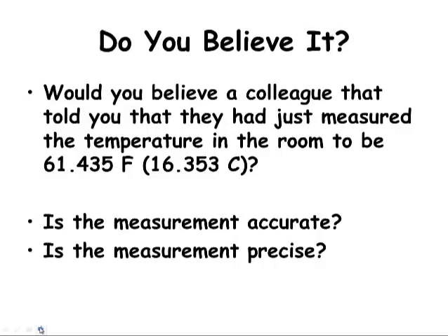It would also be important for my colleague to communicate how the temperature sensor was calibrated to such a precision and accuracy. Calibration is always important. Without proper documentation, I would question, be uncertain about what my colleague had told me. If my colleague provides the proper documentation, then I would trust the information. To answer the specific questions listed, the measurement is precise. We don't have enough information to know if the measurement is accurate.